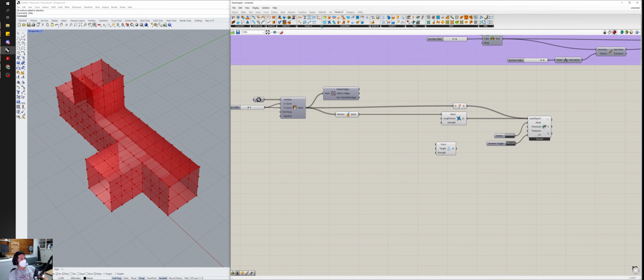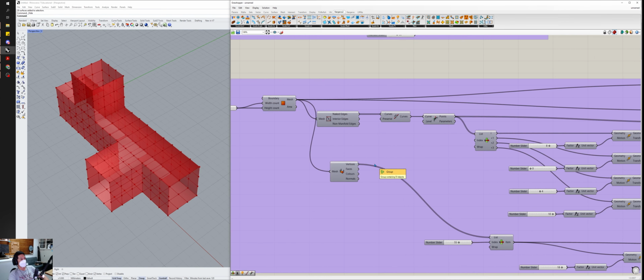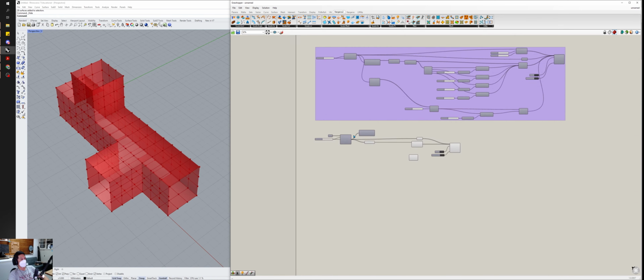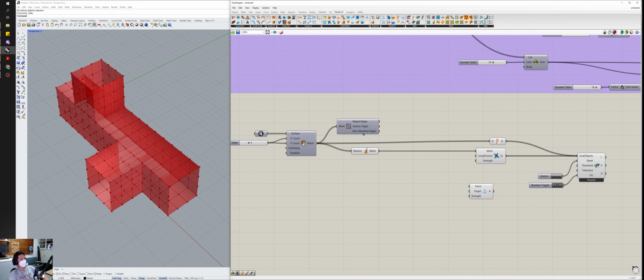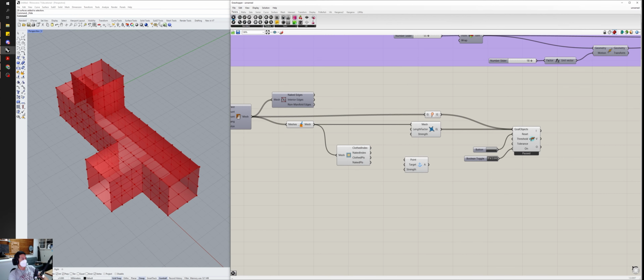In our previous example, we had talked about using the interior edge and naked edges, but that was for the mesh boundaries. Now we're working with the mesh itself. So let's go to our mesh tools, and our naked vertices under Grasshopper 2. Be sure you're using the mesh that's been cleaned up and not the original. Otherwise, the naked points will be different than you expect.